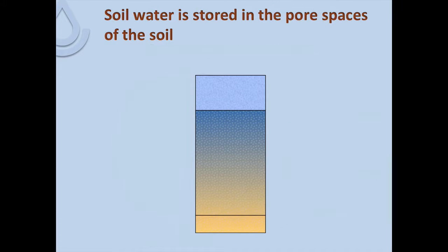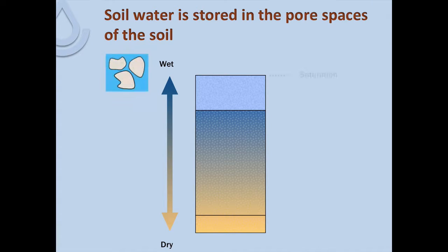Taking a look now at water storage in the soil, we can break that out into some key water content levels that are levels of particular interest. So as we look at this figure, as we move from wetter at the top to drier at the bottom, the first water content level we can look at is saturation, or when all of the void spaces are filled with water. In a true field situation, we never get to full or 100% saturation because there's always some entrapped air contained in some of the smaller pore spaces in the soil.